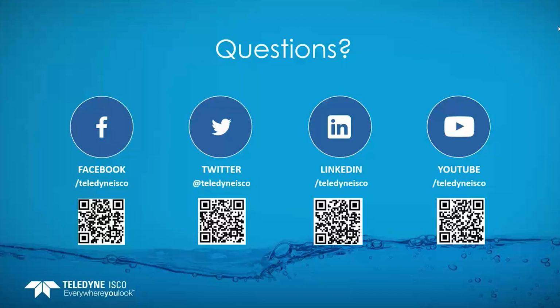Okay, very good. Let's see, Darrell, here's a question for you. What maintenance is required on the level sensors? That's a great question. So depending on which sensor you have in there, if it's an ultrasonic sensor, there's minimal maintenance required because it is out of the flow stream, but you may find that you have spider webs or other things attached to the sensor that you may have to clean off.